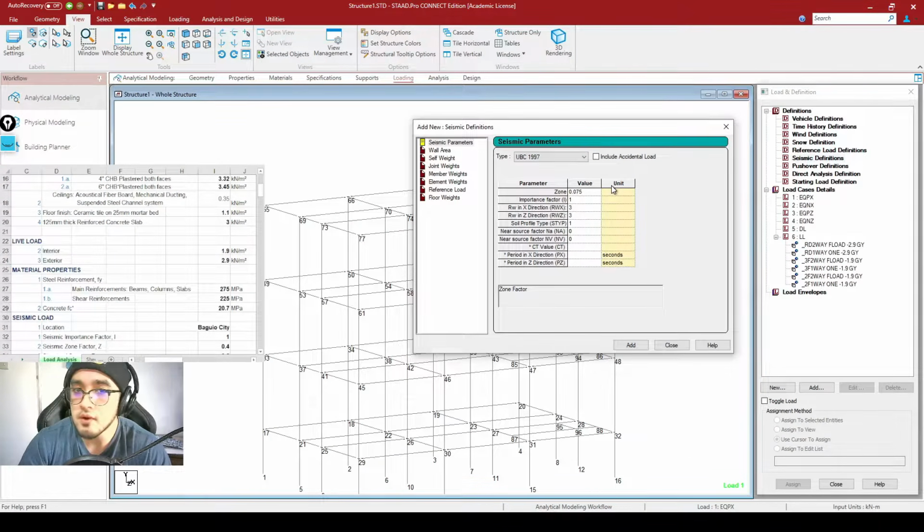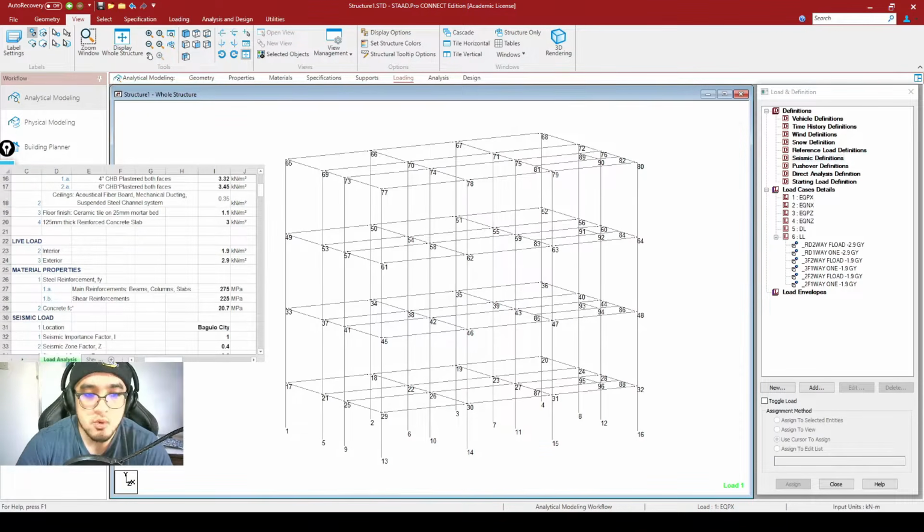Okay, but before everything else, guys, we must first take note that before applying our seismic loads, we must apply diaphragms into our structure first. But what is a diaphragm in the first place? So what is to be the use of a diaphragm? So let's say that we will be having a certain lateral load here. So let's say that it is to be directed here at this particular point right here. So what a diaphragm does is that a diaphragm would distribute or would transmit your lateral load to each of the vertical resisting element of the structure.